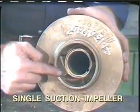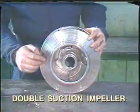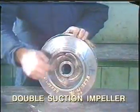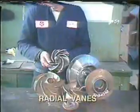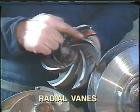In a single suction impeller, liquid enters the suction eye on only one side. For the double suction impeller, the liquid is allowed to enter on both sides. It's really like two single suction impellers placed back to back. A second classification is made by the shape of the vanes. While there are some variations, the most common by far is the radial type.